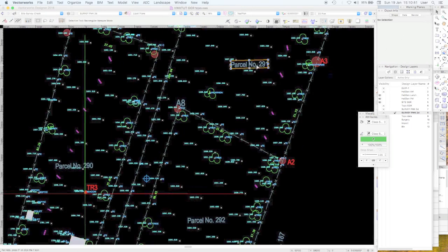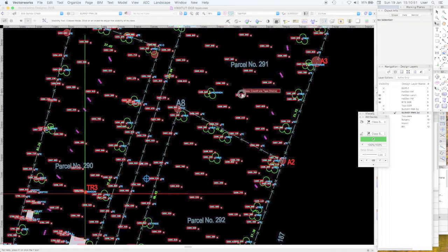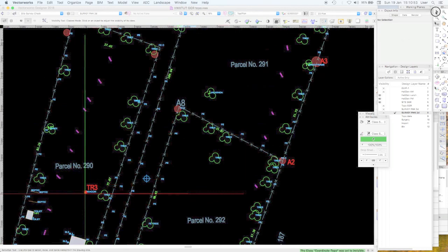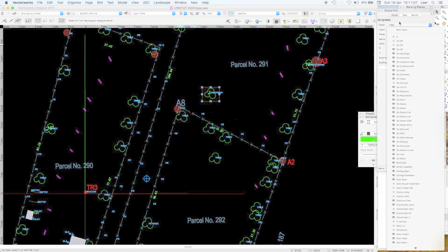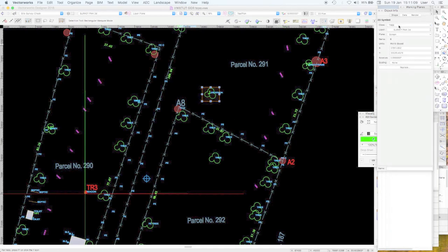So I have a bunch of these, like, okay, site text, hooray, guess what, it's text about the site. Coordinate topo, so these are topographical coordinates. You can turn those off. What else have we got? So I've converted this site party fence, so that's a fence line. This FE stands for fence and site survey text. So this is a whole lot of 2D information, and the symbols there. That's one of the imported class names.